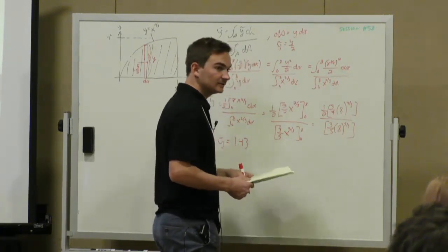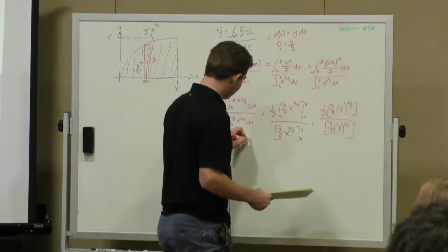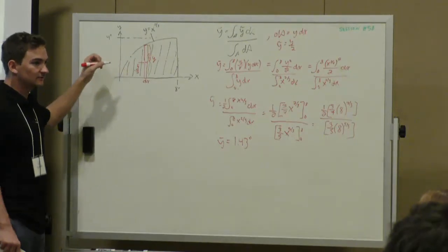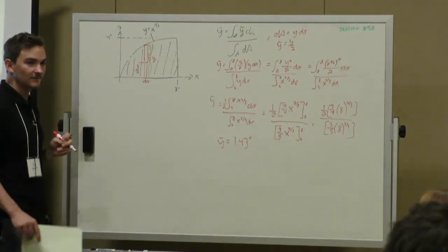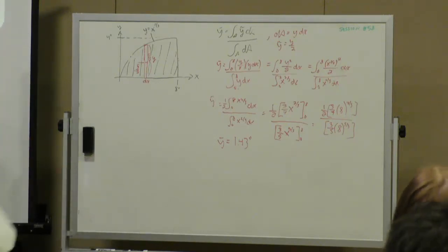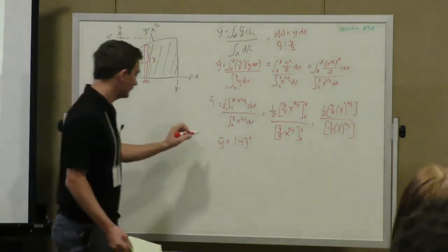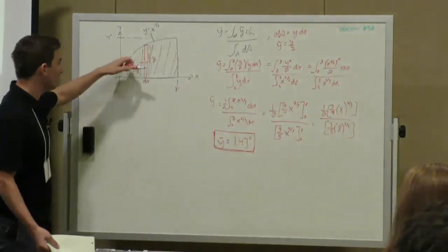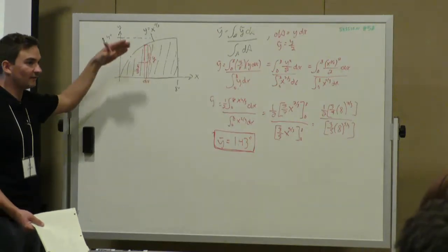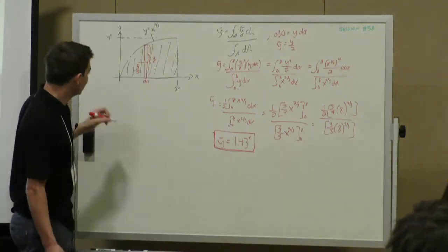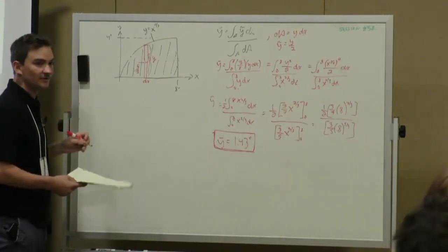What are our units? Inches. So does that make sense, that our y bar is lower? I'll let everyone finish copying real quick. So we got an answer of y bar is 1.43, which makes sense, since most of our area is lower, it should be below halfway, which would be 2. So this answer makes sense. Anyone have any questions before we move on to x bar? Okay.